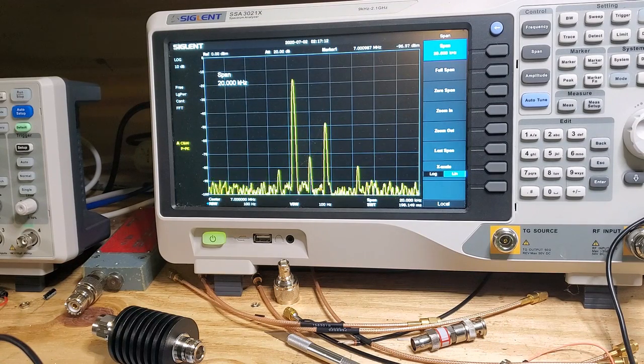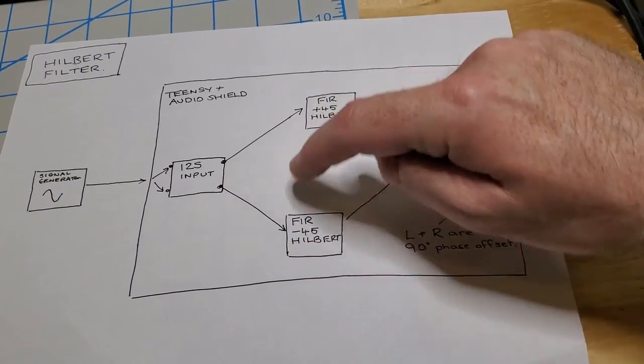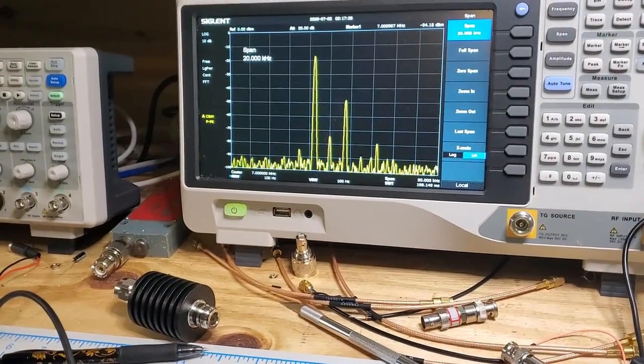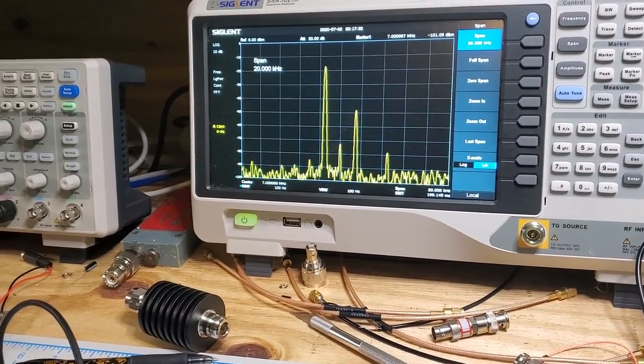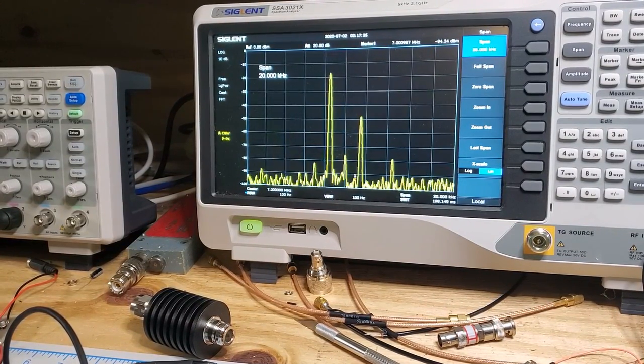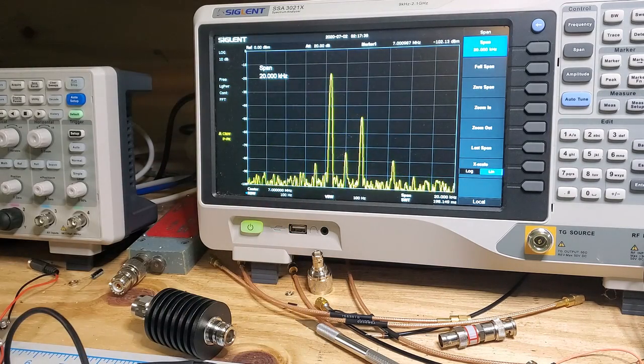There, it's restarting, and now you can see it's the upper sideband which is being suppressed. And all I did was swap over the locations of these two FIR filters in the chain here. So that basically kind of proves that that DSP filtering is working. Now, ideally, I'd like a greater degree of suppression on the unwanted sideband. It's about 26, 27 dB of suppression. I really do need a little bit more than that.